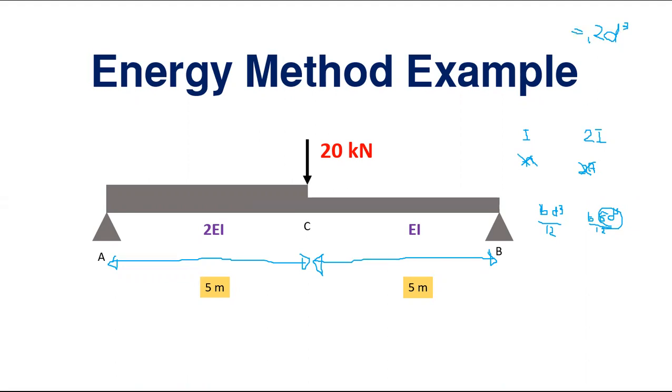So you need to take the third root of this as the D value. And then when you take the third power, it will become 2D cube. So this is a bit complex, right? You don't need to do much because you can simply multiply this by 2. That means you take the breadth value twice, because it's breadth b to the power 1. So b will become only 2b. It's the same as earlier. So if this is I, then this is 2I.